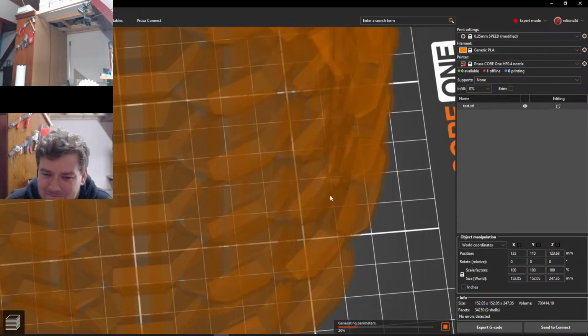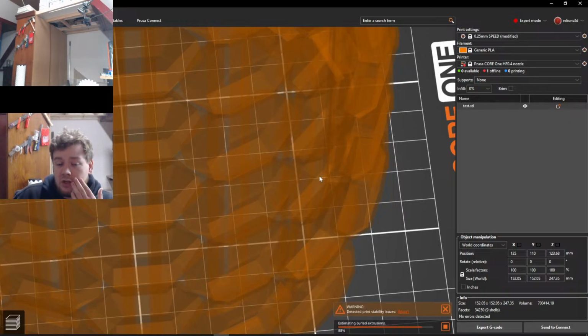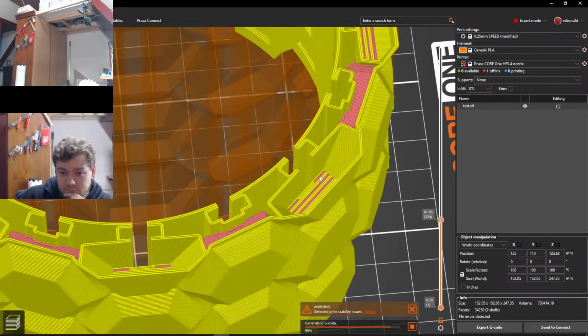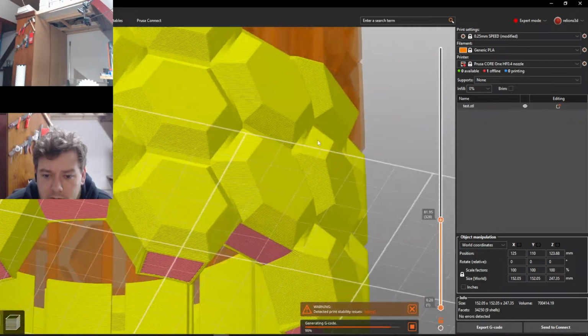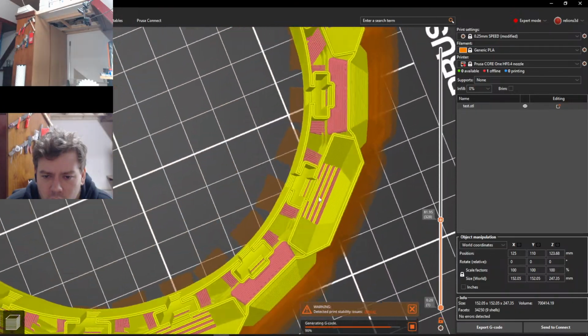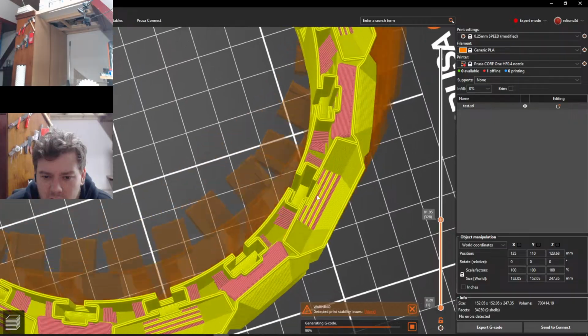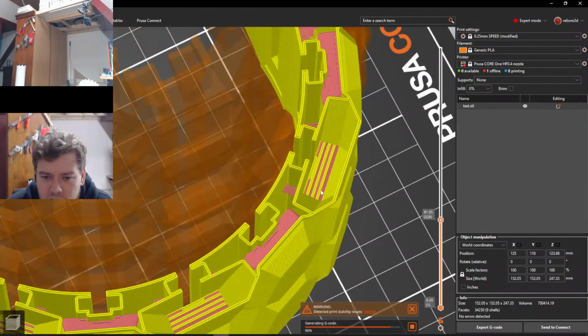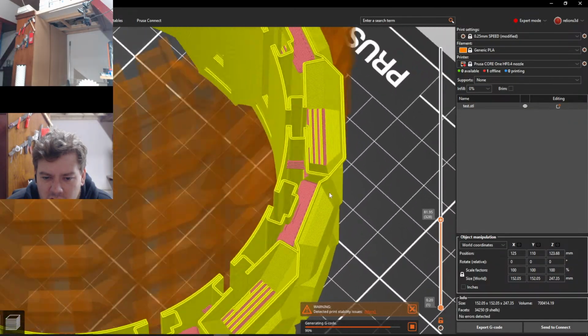And if I make a small air pocket in there that connects that area, once it's done slicing, you can do this one without infill, because then the rigidity and strength go up. Kind of curious, can you do it without infill? I think you should be able to, or is it then the bridging? Yeah, you still need a slight bit of infill.